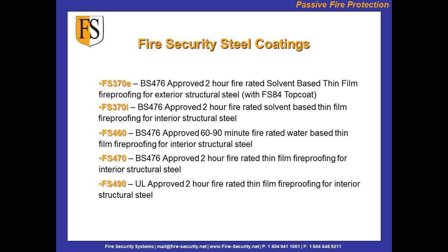But what you will find, and I haven't got this on the presentation, is that the ISO fire curve, which is used primarily in Asia and Europe and the Middle East, and also South America, is actually a higher burning, longer burning fire curve than the ASTM fire curve that UL uses.